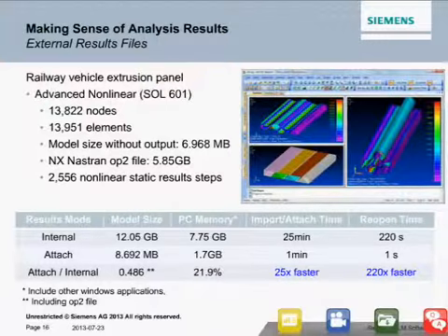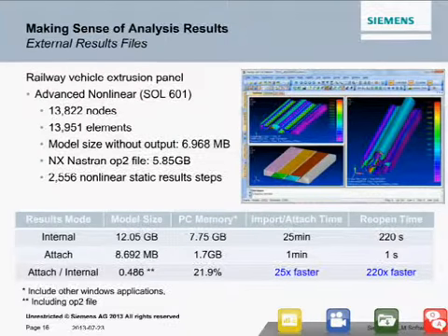Okay, so just to reiterate a couple of the benefits that we saw in one of the case studies mentioned in the video. For a particular model, the attach versus import time was a lot faster, 25 times faster, I beg your pardon. And the opening and reopening times were a lot faster as well. And the other thing, of course, was that attaching took a lot less memory than actually importing results. So a good way to deal with very large output files is to attach to them.